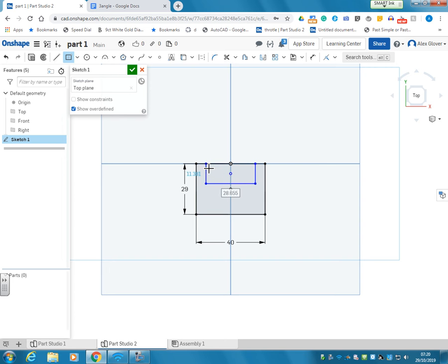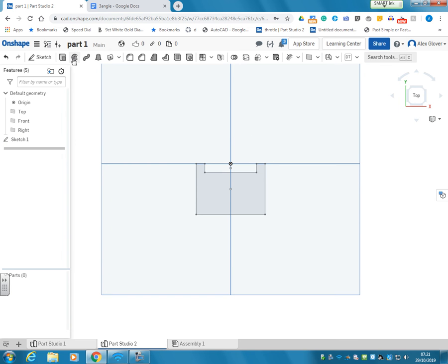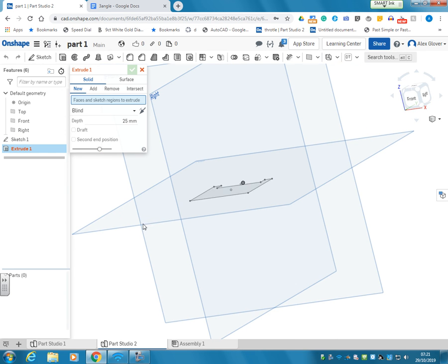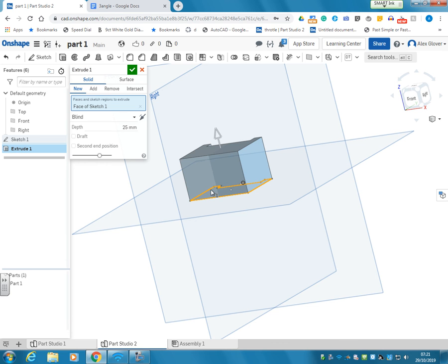Do that in the same way as the last one. Do the cuts first of all. They're in blue because we've not defined them, but the gap between here and here, just like last time actually, is 30, and this gap is 5. That's okay. Extrude this part, and the total height is 37.